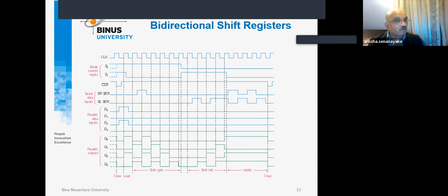You have to make external combinatorial circuits together with the clock, and sometimes flip-flops are also required, so that the pulse will be activated on time. On time means depending on the clock. For example, in this case, after the first clock pulse, second, then during the third, only then activate shift right.